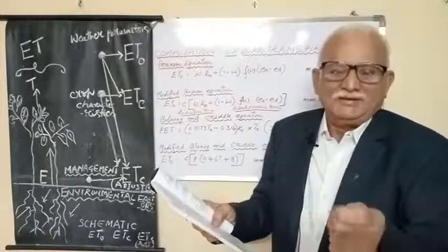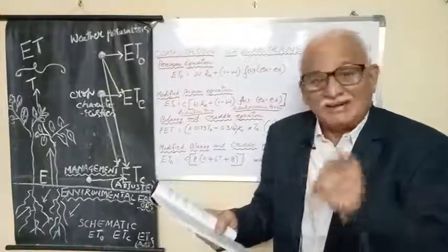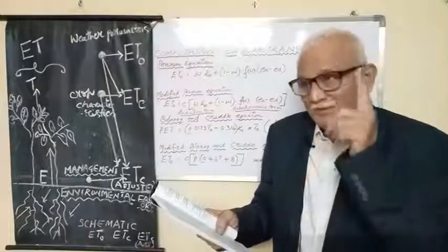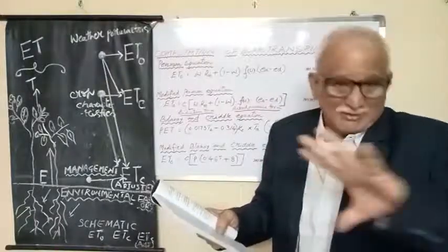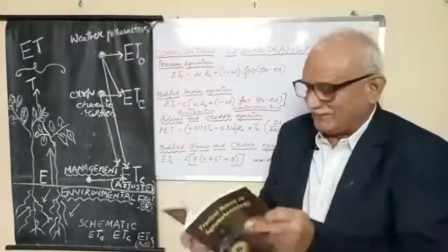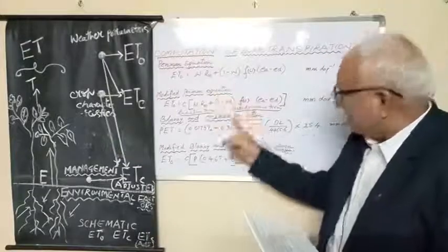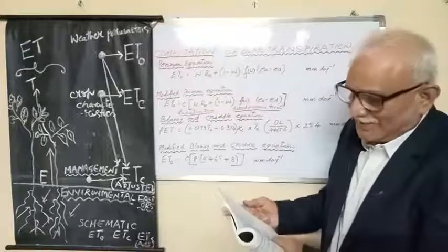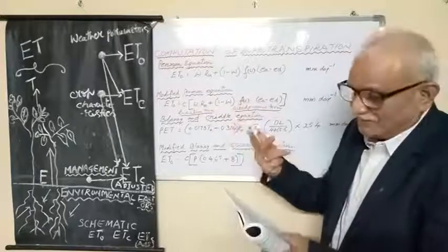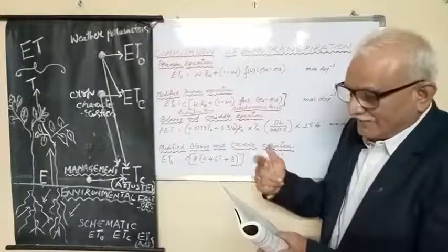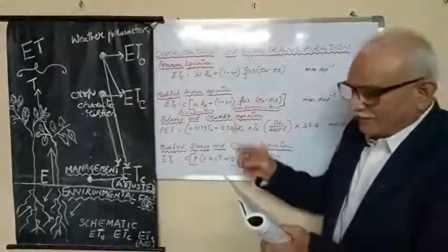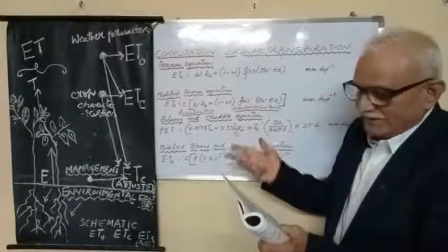Even a calculation of net solar radiation from Campbell-Stokes first, with the same equation we mentioned here. Then what is the 1 minus W? It is the same 1 minus W as in the original. So what is the FU? It's a function of the wind-related function. FU is equal to 0.27 into 1 plus U by 100.